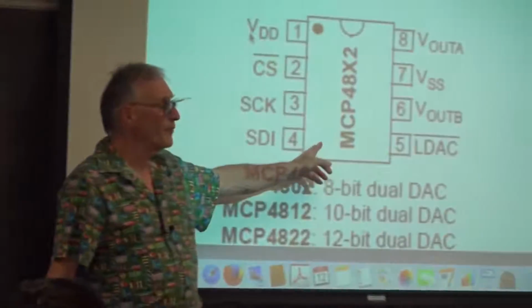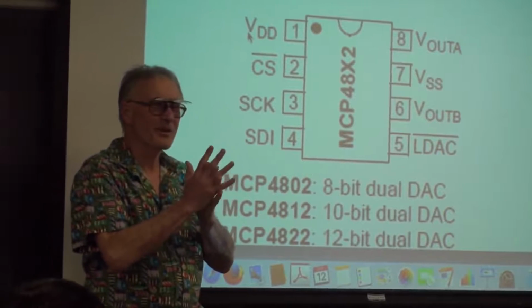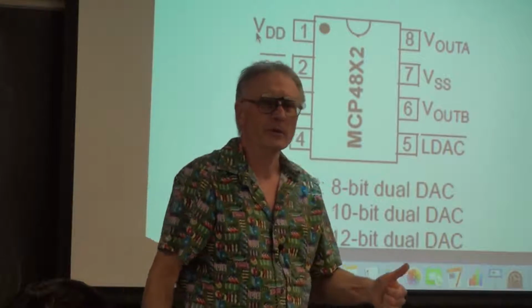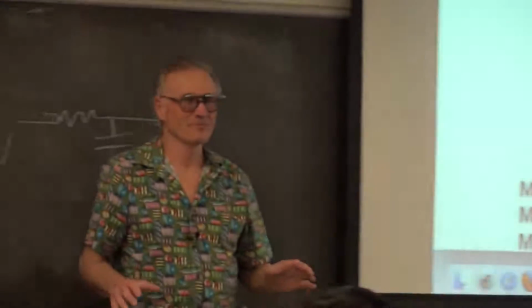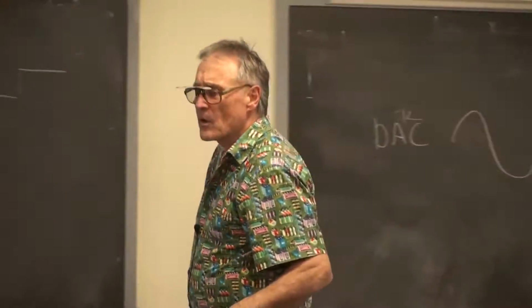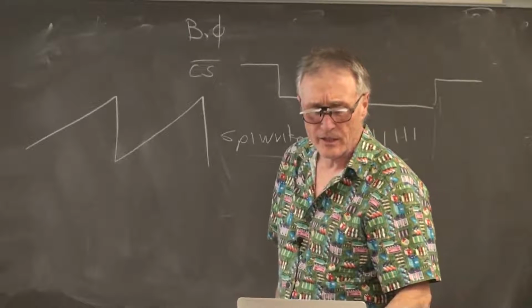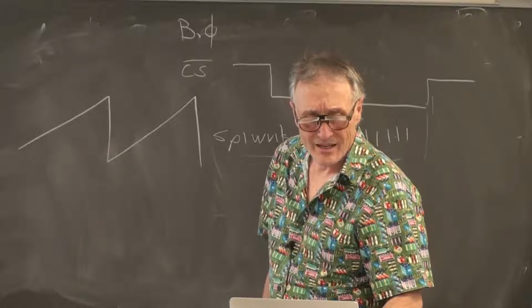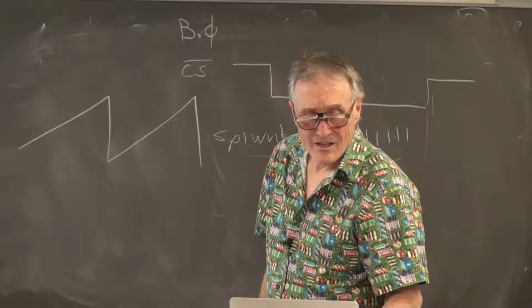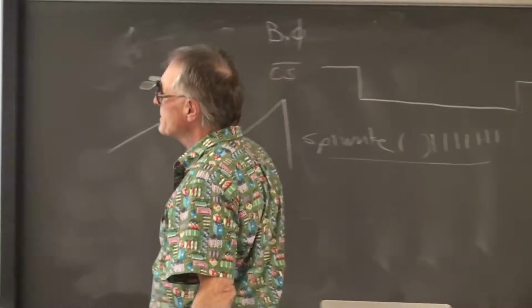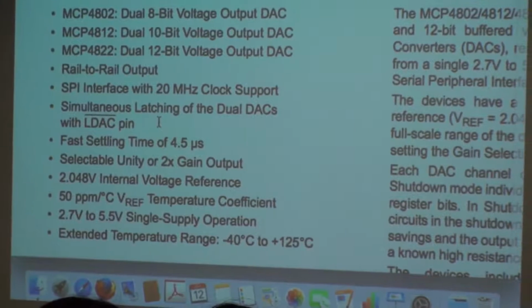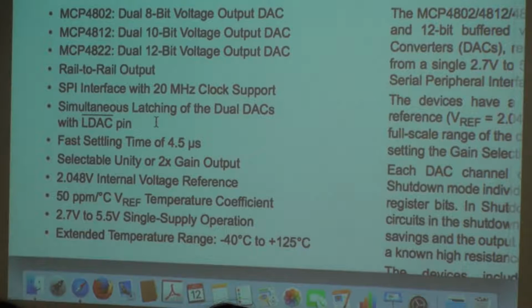Internally, there's a 12-bit voltage reference, a stable voltage reference, that gives you at gain 1 exactly plus or minus 1 volt output. It's really nice. It's fast. It's rated at 200 kilohertz, I believe. Fast settling time 4.5 microseconds, which is to say 200 kilohertz settling time. You can, however, run this at least twice as fast if you want to generate high frequencies.